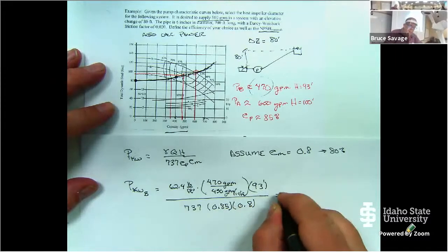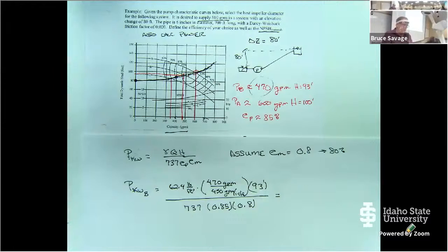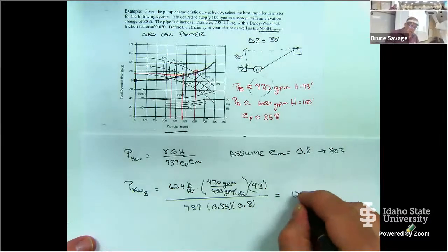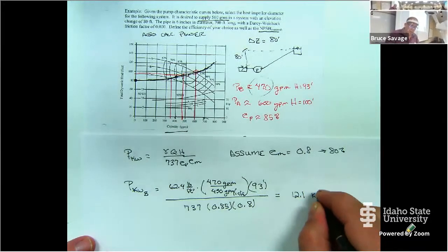And that's going to tell me how much power that pump needs to move that flow. And this tells me 12.1 kilowatts.